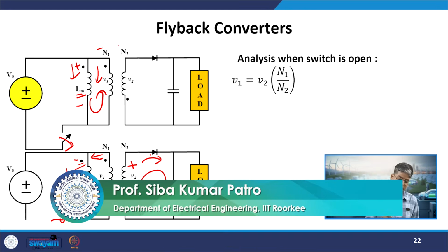That is, it is no longer restricted to between 3 to 5 times as our non-isolated DC-DC converter was. We can attain any amount of gain between the input and output voltage by adjusting the transformer turns ratio. Okay. And we have started seeing our first isolated DC-DC converter, which was our flyback converter.